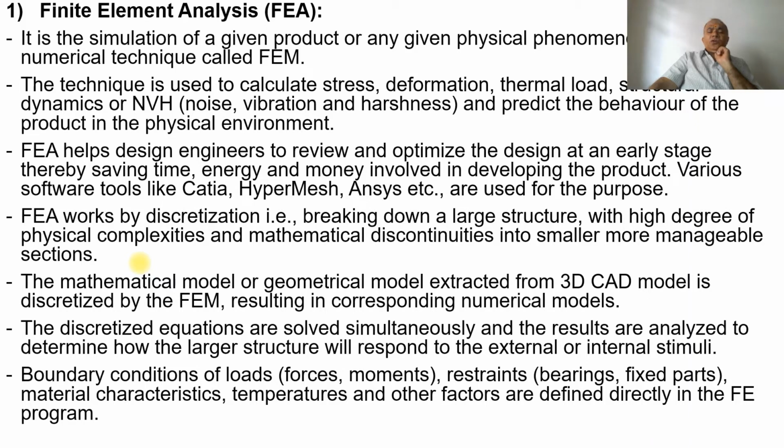The mathematical or geometrical model extracted from the 3D CAD model is discretized by the FEM, resulting in corresponding numerical models. Discretized equations are solved simultaneously and the results are analyzed to determine how the larger structure will respond to external or internal stimuli.